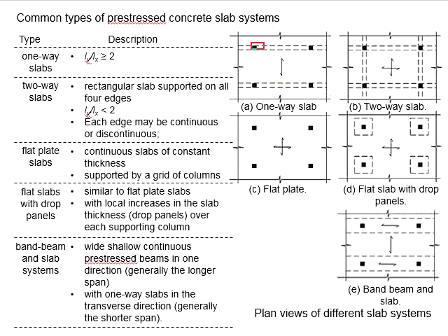Due to the absence of the beams, this kind of slab normally has problems with punching shear due to low effective depth of the slab. Therefore, if you are designing a flat slab, the punching shear will be one of the critical conditions that you need to check.